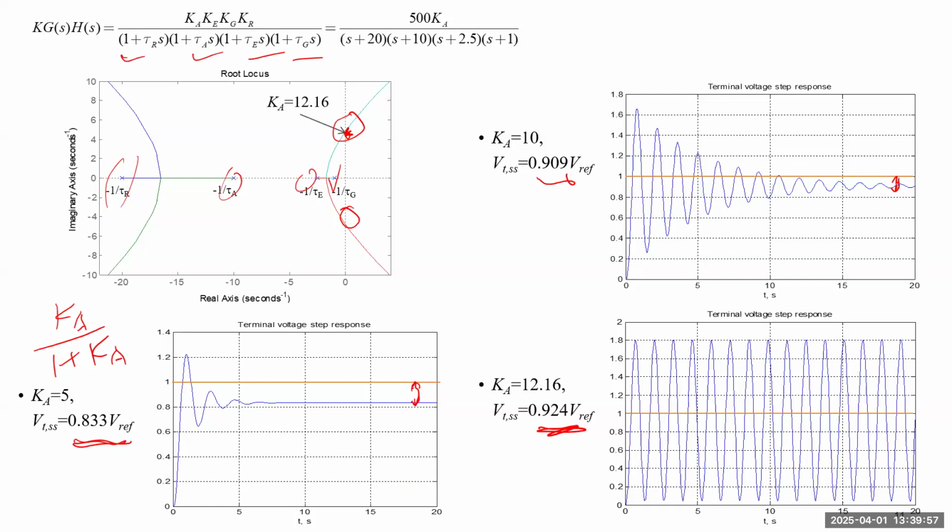So now we know for this system, if the gain is around 12, the system is going to lose stability beyond that value. So what you can do is add another pole. Once you add another pole, each root locus will shift. They still follow a number of formulas which we covered. If I give you the location of the open loop transfer function's poles, how do you roughly draw each root locus?